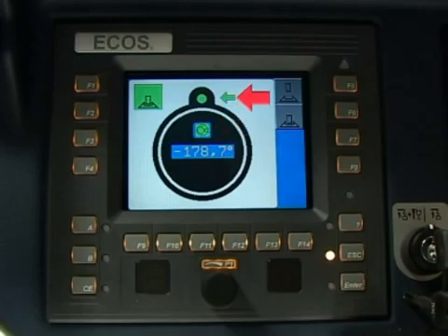This symbol is shown within plus or minus 20 degrees of a locking position and indicates the required slew direction to the locking position. Two opposing arrows indicate a locking position. These symbols show the status of the locking pin. Green is locked, yellow is in transition, red is unlocked, violet represents a system error. Let's now operate the house lock.